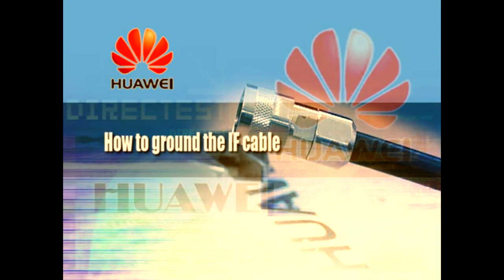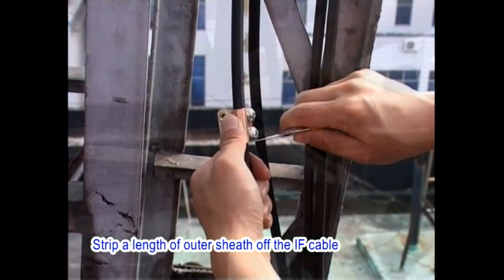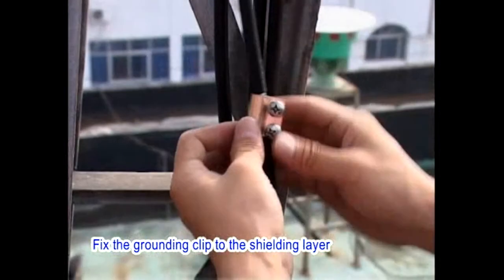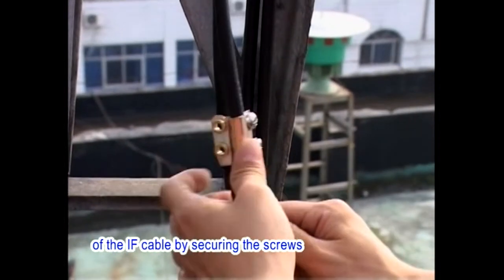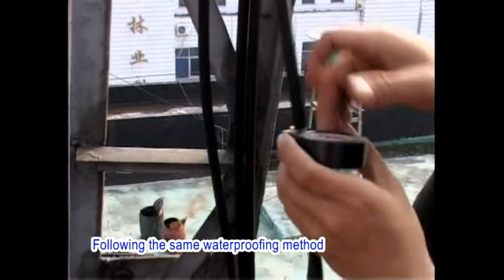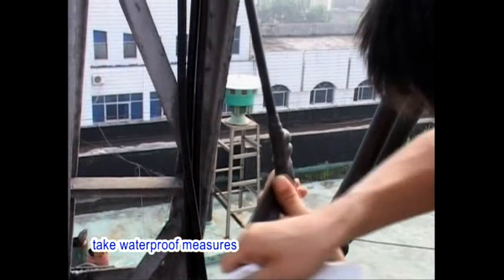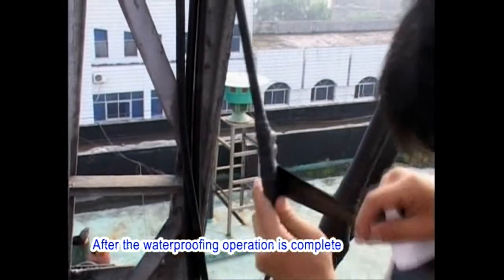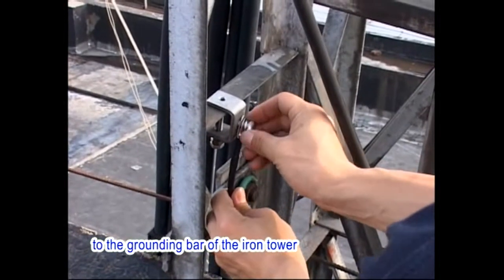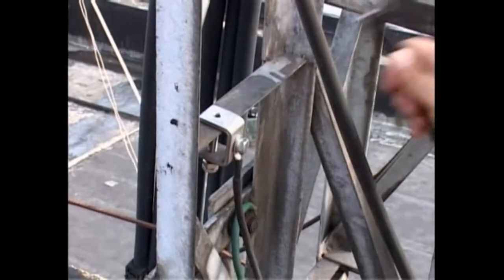How to ground the IF cable. Strip a length of outer sheath off the IF cable according to the width of the grounding clip. Fix the grounding clip to the shielding layer of the IF cable by securing the screws. Following the same waterproofing method as described previously, take waterproof measures. After the waterproofing operation is complete, fix the other end of the grounding clip to the grounding bar of the iron tower or directly to the iron tower.